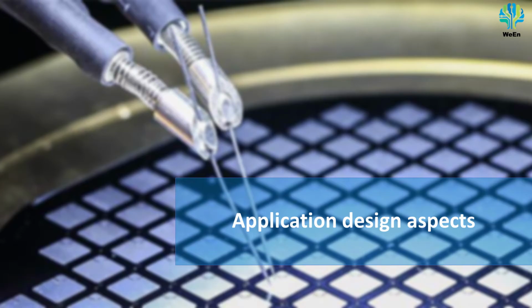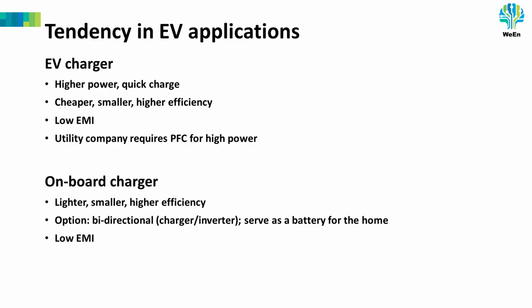Now we have a look at application design aspects. Let's have a look at tendencies in EV charger applications. For the EV charger, it is important to have a high power so you can quickly charge the vehicle. Over time, they should become cheaper, smaller, and run at high efficiency. EMI is always important. The application should generate as little EMI as possible. And of course, we need to apply PFC because this is a high power application and the utility companies will require PFC.